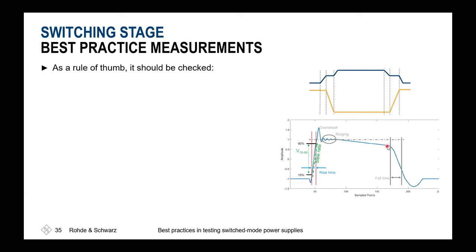Also, a voltage drop might be of interest for you, so meaning what's the relation between the high value at the beginning and at the end of your measurement. If you're comparing the slew rates or maximum slew rates that could be measured and the rise times that could be measured with the given intrinsic rise times of your oscilloscope, please always be aware, an oscilloscope is always specified to measure at 10-90 value. If your definition of your DUT gives you a 20-80, 25-75, doesn't matter.